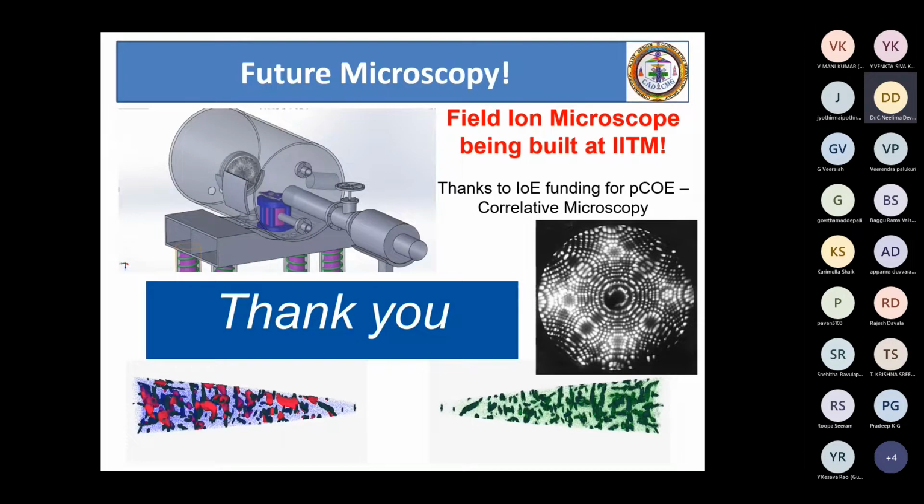And especially with respect to additive manufacturing, you said, sir, this characterization technique is being used for additive manufacturing, especially for nickel, aluminum, bronze materials. Yeah, I showed an example of nickel, aluminum, bronze, but we do it on other materials also, like maraging steel, a lot of different additive manufactured materials, because all additive manufactured materials are in a non-equilibrium state. So you can expect chemical heterogeneity across the volume that is being prepared. And correspondingly, when local variation happens, we can always expect different nanoscale features to be present inside.